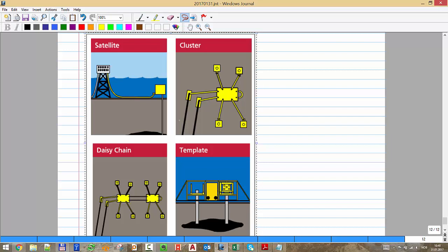But you still see you have the two lines, and the lines, the pig, they have to be the same size, because the pig has to be able to go through both of them without any problem. So the two of them have to be the same size, and here you have the loop, the pigging loop. And here you see they want to use the same arrangement. For example, they want to produce all of these wells through these two lines, and they also want to have pig. When they pick one, they also pick the other at the same time. So that arrangement is called daisy chain.